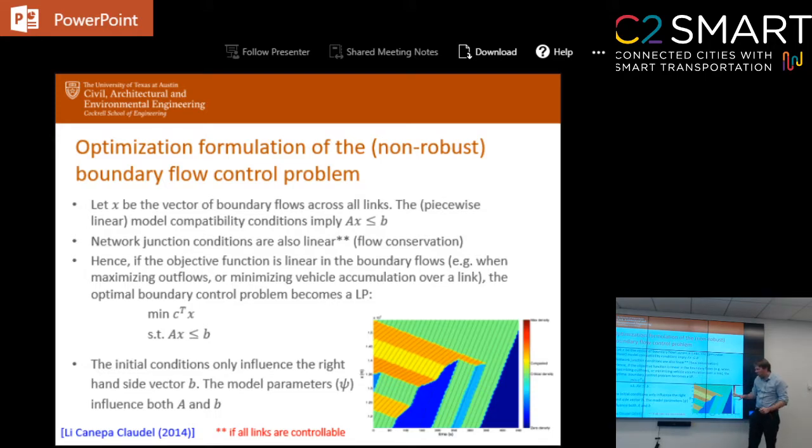You actually have a lot of freedom to find the set of boundary conditions here that will maximize the flow, because as long as you send enough cars so that there will always be a maximum flow out, the flow here will be maximized. So you can, for example, stop sending cars until the congestion is clear, and then keep sending the max flow of cars. There are many ways to get a solution here. The solution usually is not unique, and there are many combinations of flows that give you the optimal solution.